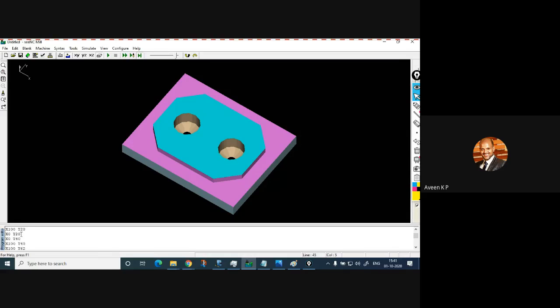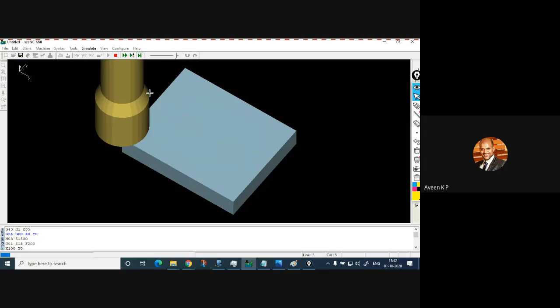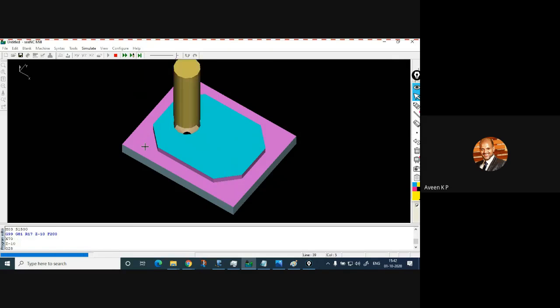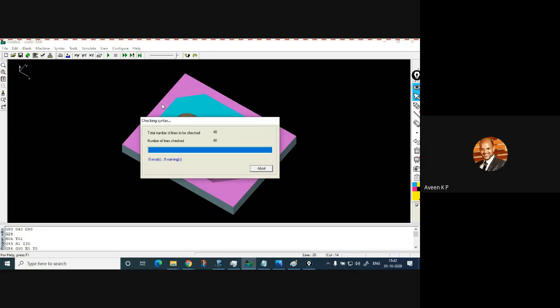Okay, no problem. So this is done, and again if I check the initial position of the second tool, please check the first portion here. Here you can see the red mark. That is indicating something is not happening as per the format. So I will change that. Y minus 15, I will give a little more away, let me give 30 away. I have made a modification in my program, and you should make sure that you run the program again, then only it will consider. So you need to run the program again.